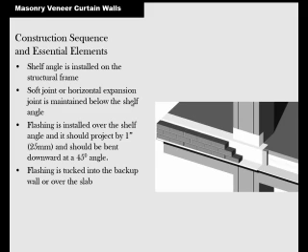So what do you do for a masonry? Like this building is a masonry veneer. I don't think the masonry on the outside of this building holds anything up except itself. It's built on a structural system. There's columns, and then there'll be angles that the masonry will sit on, probably for each story.